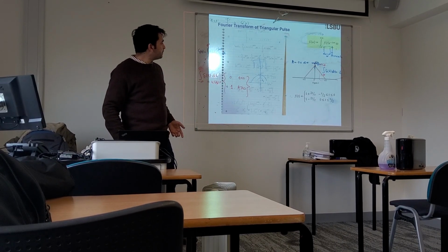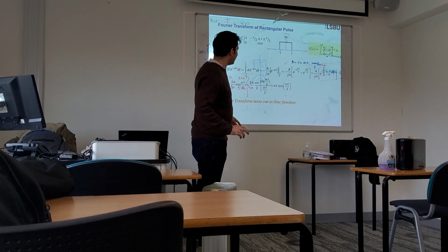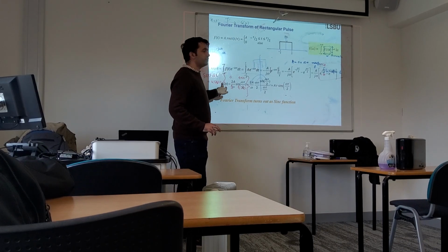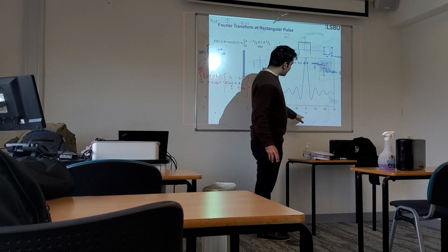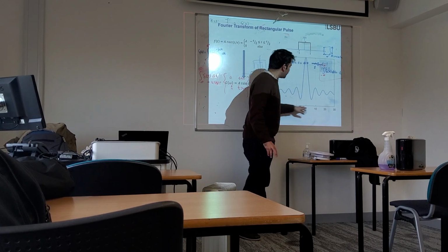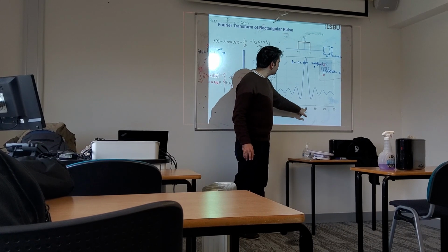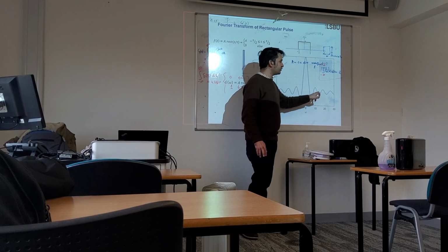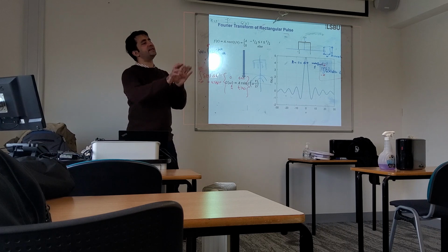If you remember in the previous case, consider that this was a noise signal, just for the sake of understanding. So we come up with a final frequency domain signal. And when we plot this frequency domain signal, now I can see what the frequencies are and what their magnitudes are. Now you can see at 0, I have 10 magnitudes, at minus 10 hertz and at 10 hertz as well. So from here I can see what the different frequencies in that noise signal are.